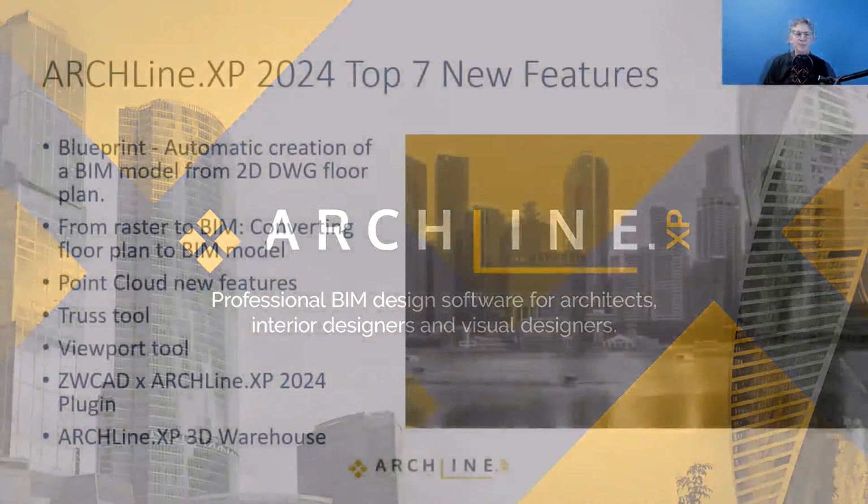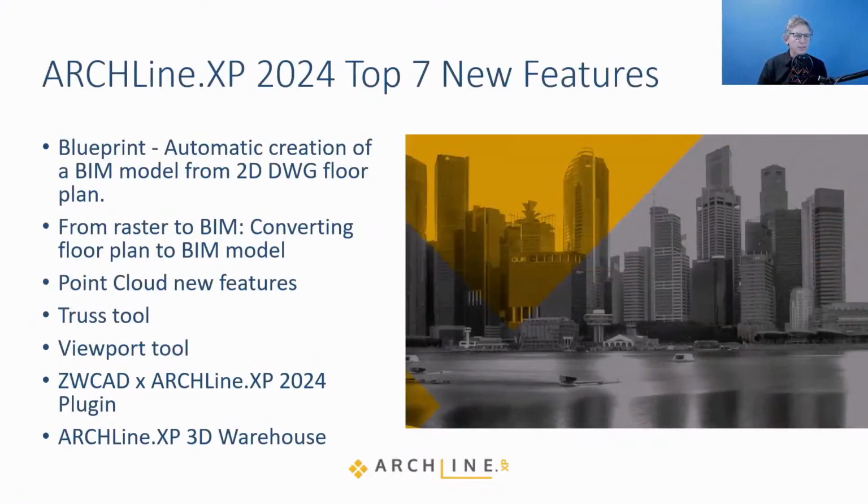Let's go! The top 7 new features. Blueprint. Blueprint is a true original innovation. ARCHLine XP 2024 automatically generates BIM models from 2D DWG floor plan, from raster to BIM, converting floor plan to BIM model. Point cloud new features are the RCS and the LAS format management. We have 2 new tools in the 2024 version, the Truss and the Viewport. We renew the ZW-CAD ARCHLine XP 2024 plugin. And finally, we have a very new warehouse. We call it ARCHLine XP 3D Warehouse.